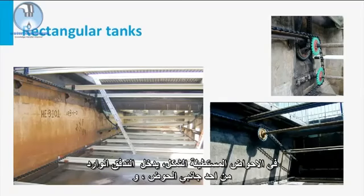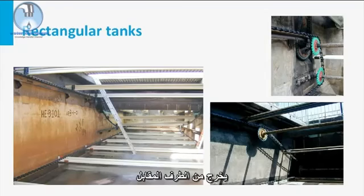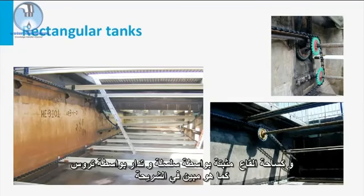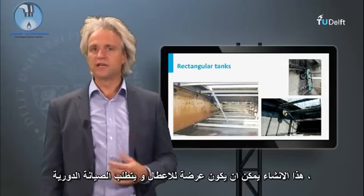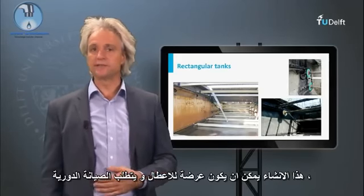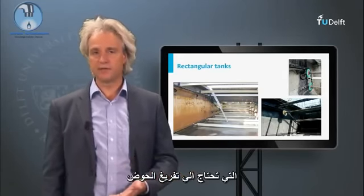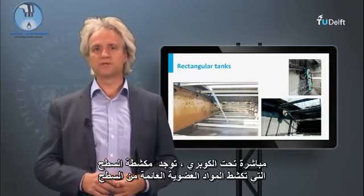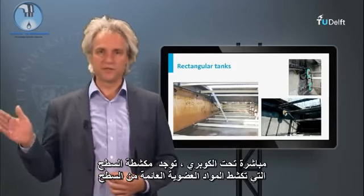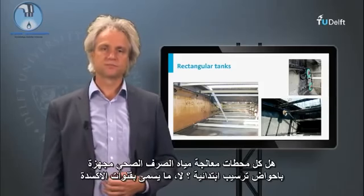In rectangular tanks, the inflow is distributed at the lateral side of the clarifier and leaves the tank at the opposite extreme. The bottom scrapers are mounted on a chain which is driven by gears as shown in the slide. This construction, however, can be vulnerable and regular maintenance is required, for which a tank needs to be emptied. Directly under the bridge, a surface scraper is mounted to skim the floating organic material from the surface.